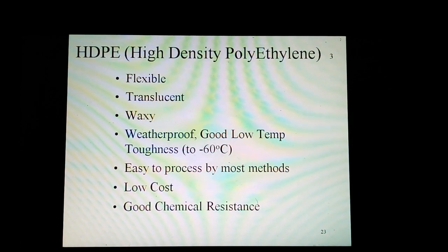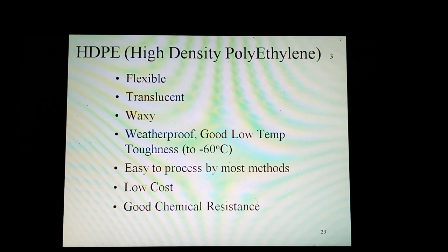HDPE, or high-density polyethylene, is flexible, translucent or waxy, weatherproof, and has good low-temperature toughness down to minus 60 degrees centigrade. It is easy to process by most methods. It is low cost and has good chemical resistance.